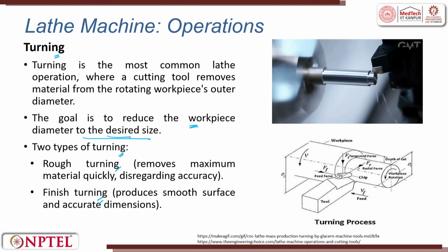When we try to do fine turning, the feed rates are smaller and the depth given is also very small. In the sense it will be 1/10 of the rough turning you will try to do in a finish, such that you get a smooth surface finish.